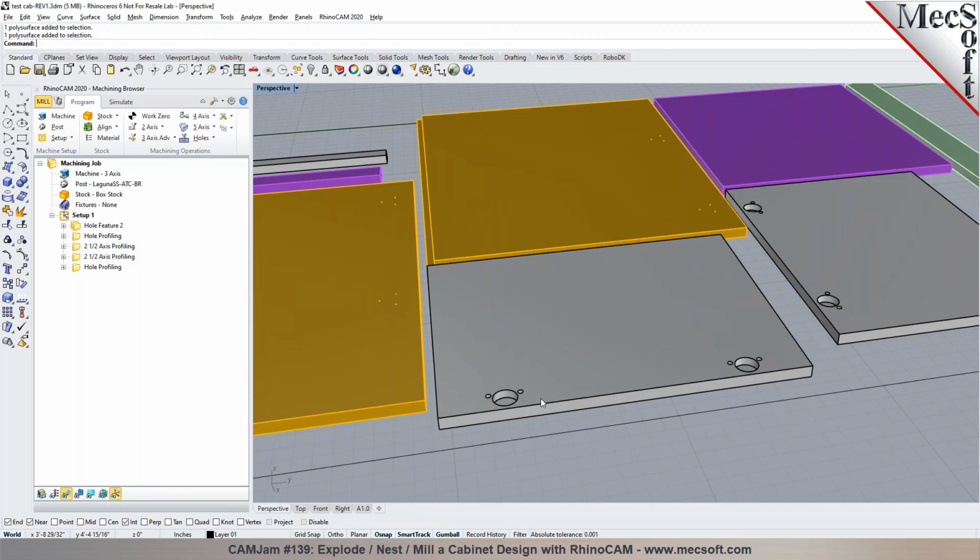So because these pockets, these big holes right here, are for hinges, say all of a sudden I decided I wanted to change the type of hinge and needed to make different holes. I could just do that right here. You're still completely inside of Rhino, and you can make those changes. The only thing is the features will be deleted when you make a design change to the solid part, so you have to detect them again. If you're working with curves, then you just reselect the curves for machining. If you added a feature or made a change, you just reselect them. Awesome. All right. Okay.